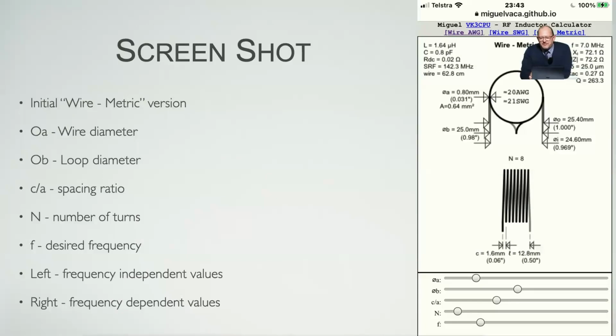Interestingly, when I first got into this, my experience with wires was really from Jaycar Electronics and buying the 0.5, 0.25, 0.8 millimeter or 1 millimeter, 1.25 millimeter wire. So in my head, I always had that wire was available in metric sizes. And once I dove into it, I realized actually they're not. There's no such thing as metric wires, right? There's these two standards, AWG, which is the American wire gauge, and then there's the standard wire gauge, which is close but not quite the same.